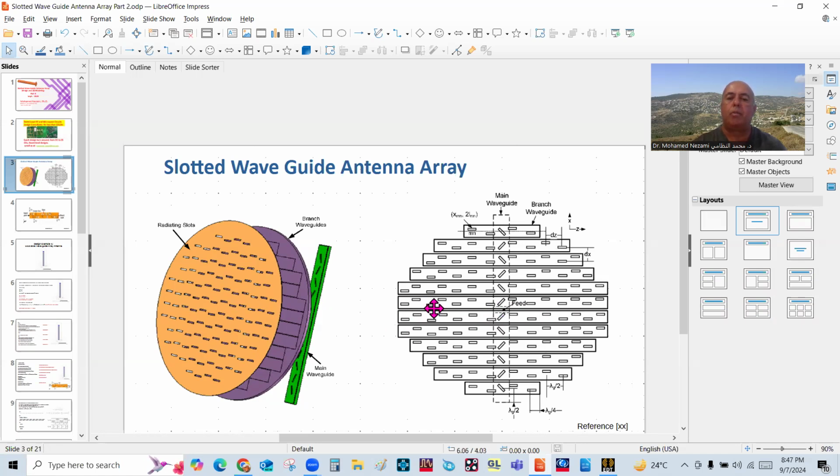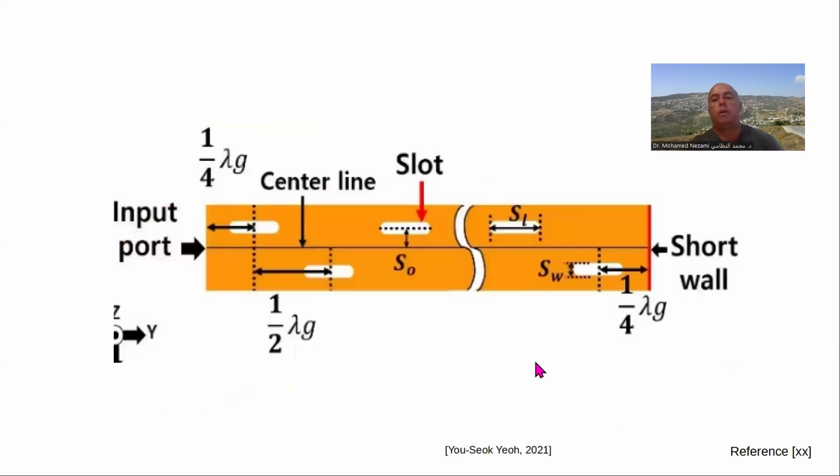I'm going to stack a number of them and then taper the waveguide length down like this so that I can get a circular beam like this, very narrow beam, okay? And then I'm going to build another waveguide behind that feeds the RF signal to all of these slotted stacks via another waveguide behind with inclined slots. So now let's just review how we're going to do this.